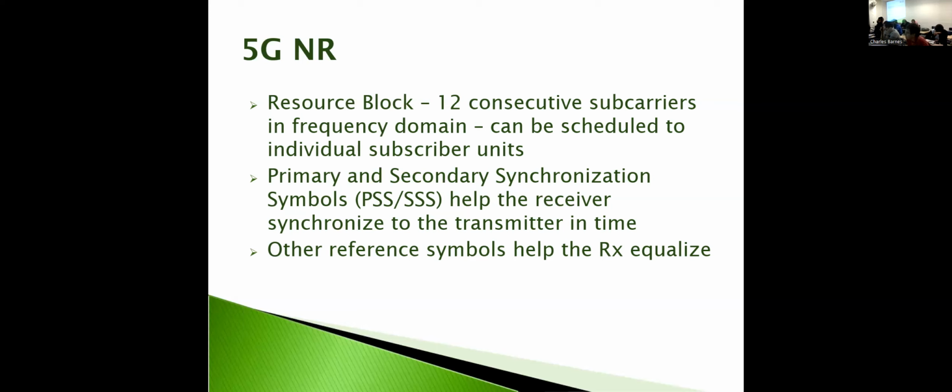Why don't we go down to one, each subcarrier? Well, all that signaling gets more verbose then. If I'm divvying up 4096 subcarriers by 12, I need a certain number of bits in my packet to describe which of those 12-subcarrier groups are yours. But if I'm having to go all the way down to each individual subcarrier, I need even more bits.